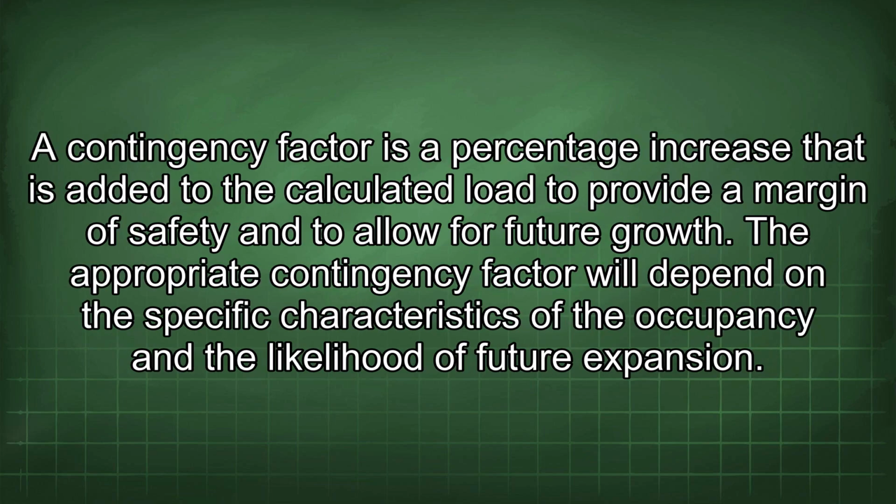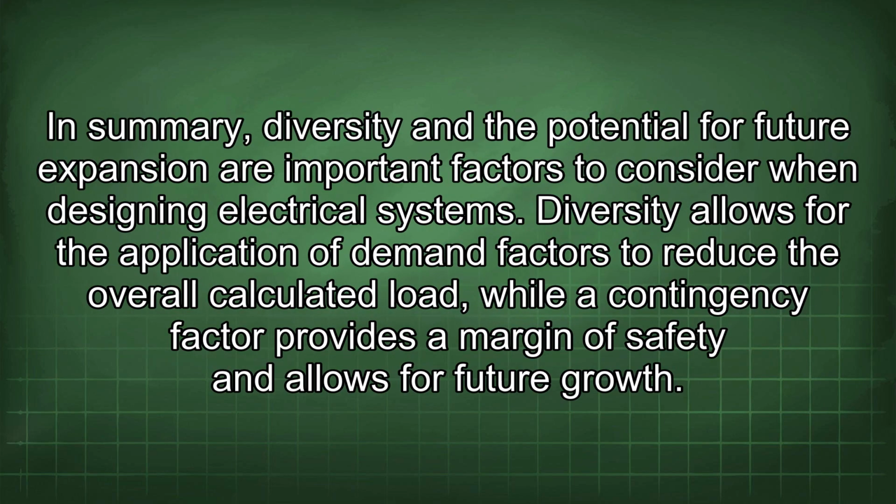A contingency factor is a percentage increase that is added to the calculated load to provide a margin of safety and to allow for future growth. The appropriate contingency factor will depend on the specific characteristics of the occupancy and the likelihood of future expansion. In summary, diversity and the potential for future expansion are important factors to consider when designing electrical systems.